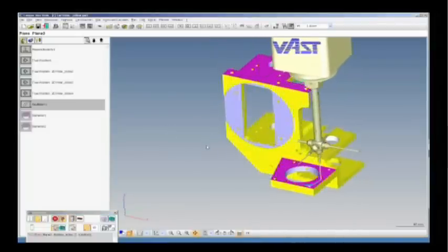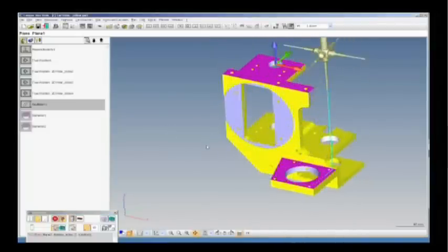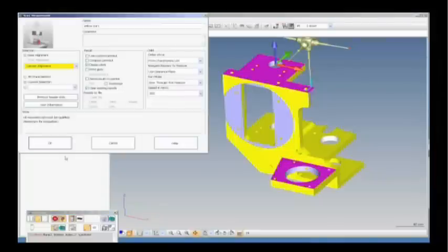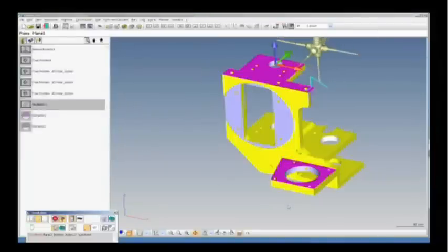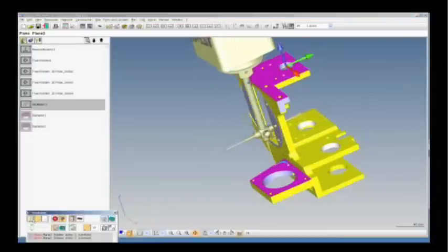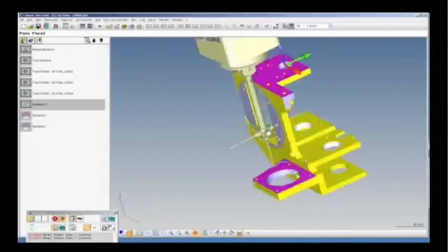This is an actual simulation of what the CNC machine, the CNC CMM is going to do, how it's actually going to move the probe. Yep, it's almost in real time, and it will move exactly as we're seeing it right here. Okay. Pretty good tool, because as that was running, and let me run it again here. There's a small collision happening right about here. Oh, okay, I see it. Yeah, so it went right through the wall. Yeah, that's not going to work.